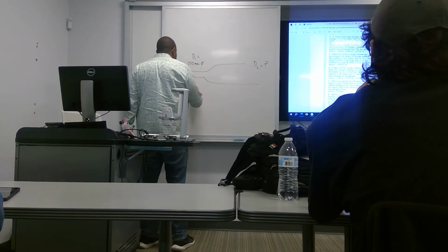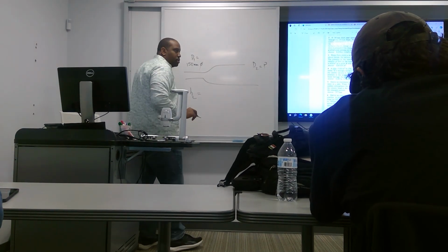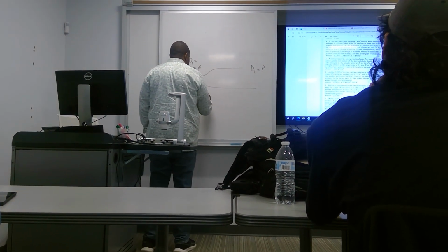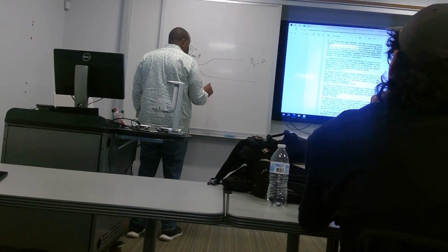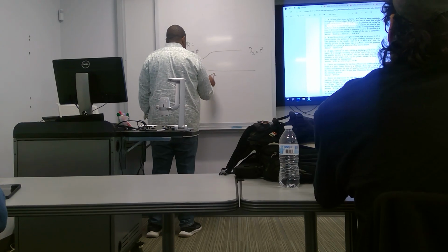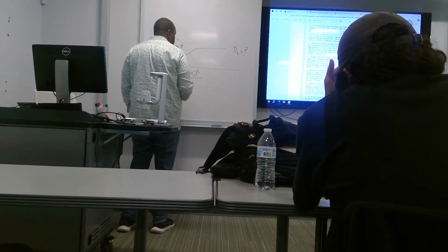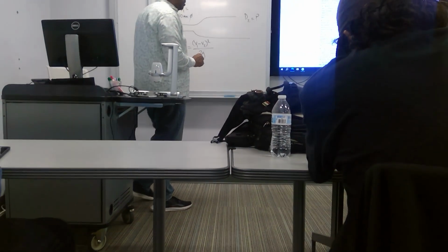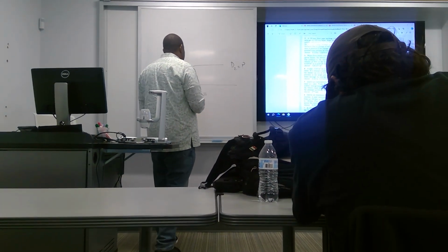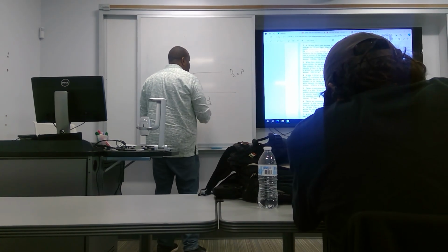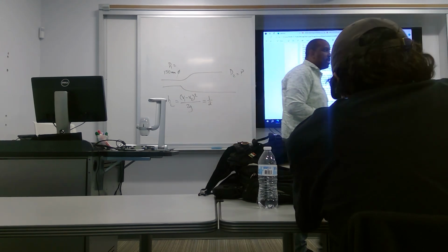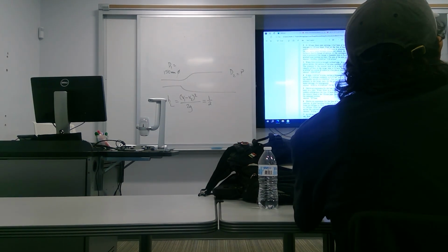You know that the head loss is equal to (V1 minus V2) squared over 2g. And they tell you that the head loss is equal to 1/2 of the velocity head in the 150 millimeter pipe. What's the velocity head? V1 squared on 2g.